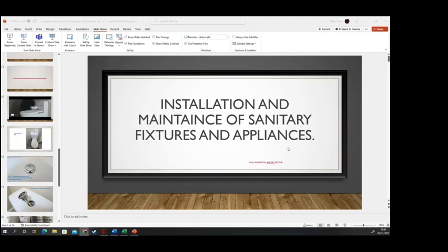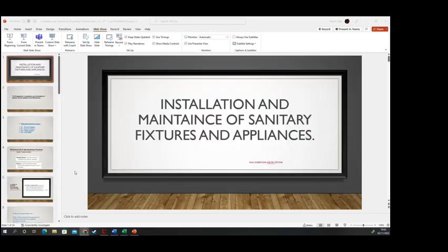And obviously they want it done now, not in a week's time. An old tap doesn't necessarily tell you very clearly what cartridge it's got in it, or what specific brand it is. So unless you've got it in your stock of half a dozen that you might have, replacing it with a new one would probably be the go. Then all the chrome and everything else is like new as well. You're not coming back.